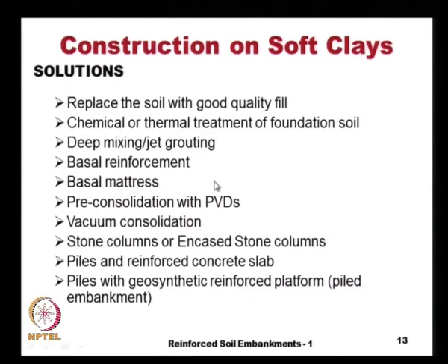What are the different alternatives for construction in the soft clays? If the thickness of the soft clay is not very much, the easiest solution is to replace the soil with a good quality soil. We just simply remove all the soft clay and then replace it with some good granular soil, or we can use a chemical or a thermal treatment of the foundation soil, so that we can increase the strength.